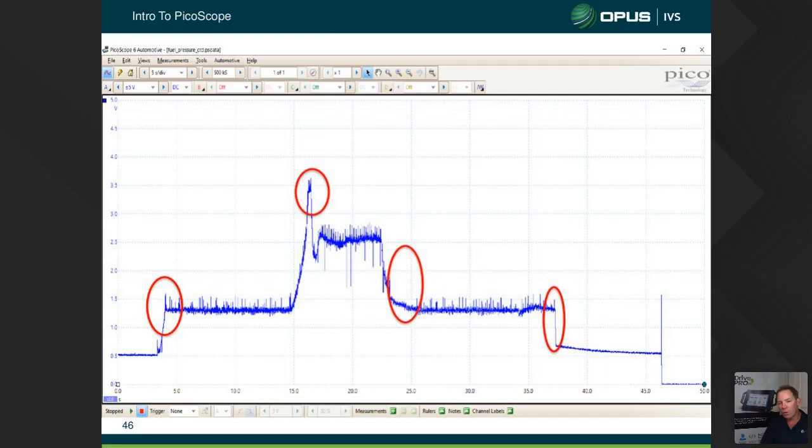So you can see I've held it open for about 5 seconds, which is what the instructions said. Then I've backed off the throttle. Now, when I back off the throttle, I should see that fuel drop down, and it should ramp back down to our idle pressure. If I don't see that ramp back down nice and smooth, if I get a jagged edge across here, that could be my suction control valve sticking. Or I might see it stay up there when I back off. And again, that's the suction control valve sticking. That's a good way to test the valves.